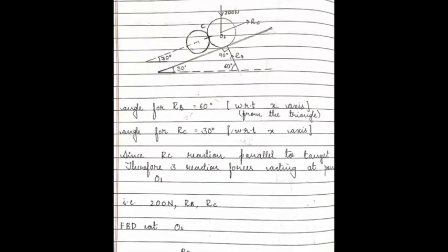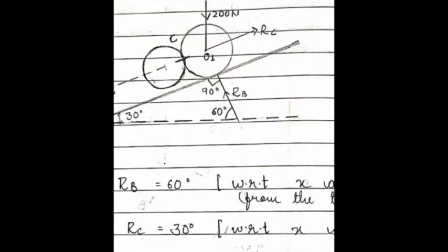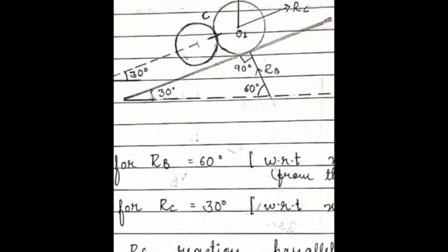You see that figure clearly. See, after giving those notes, you need to understand. Likewise, I have written it. Please concentrate looking at the figure. See, O1, before drawing the free body, you should understand how it looks exactly. Number one is RB. RB is moving towards the second quadrant. You know, there is a line, we call it a tangent. 90 degree will be there, any line which means exactly 90 degree. Already the 30 degree on one side has been given. You can frame a triangle, yes or no? 90, 30. The remaining is how much? 60. Therefore, the angle for RB, which is in your second quadrant, is your 60 degree.